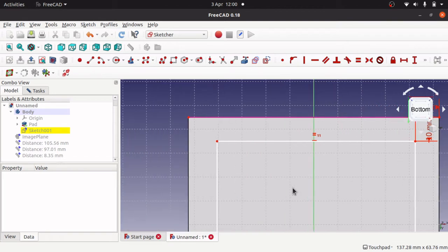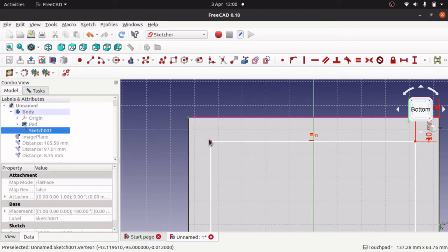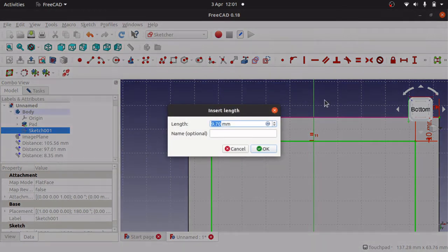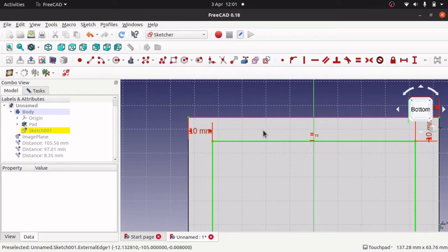So that will actually mean that because those two sides are equal, then here and here we can actually move that and just put one constraint in there. So from here and here, do a width of 10, and then that's all locked down. We don't have to worry about the height because it's already constrained over there, and we've also got our equality constraints in. So that's fixed now.